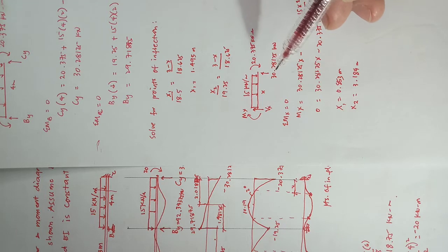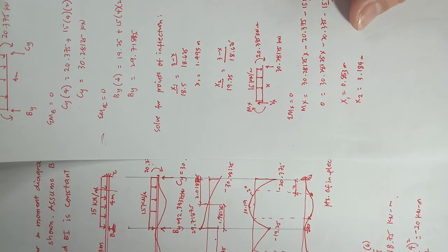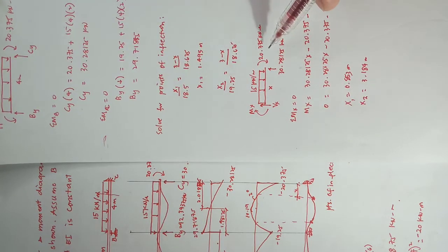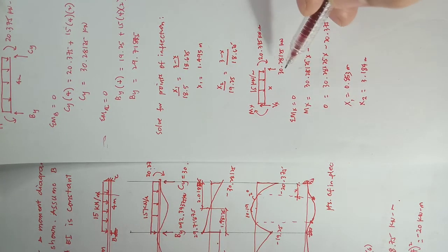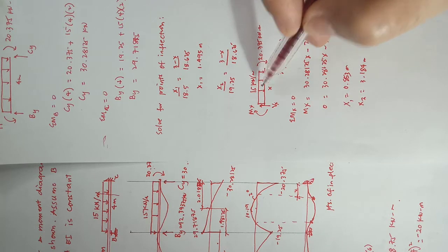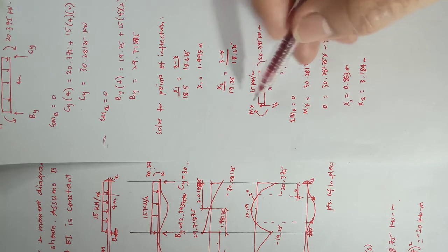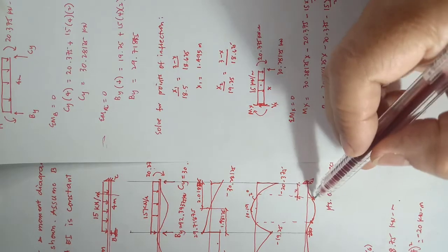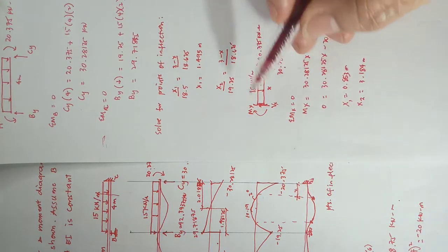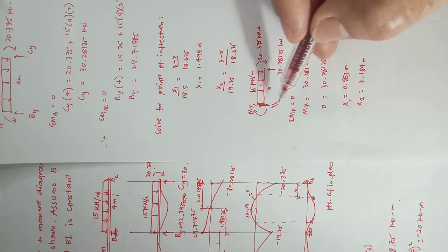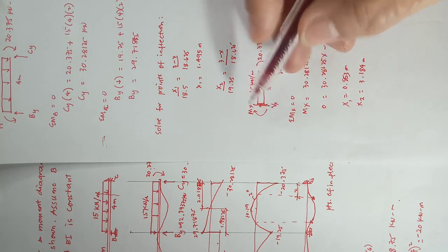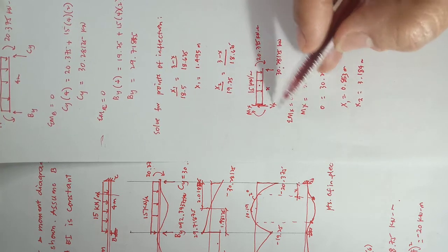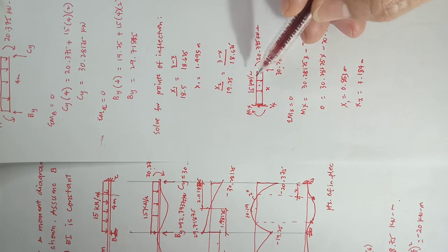Okay? As shown in our beam, you have a moment at C equal to 20.375, then your reaction, your load, and consider this distance x. So since you cut that point, which is the 0 moment, so you will have there shear at x and the moment at x. So sum up moment at this section equal to 0.